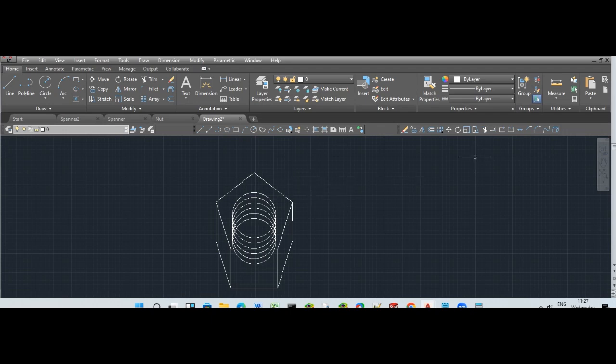I will click this tool here, click the trim tool, select the first one, and press enter. Then I'm going to trim the other ones with respect to this. So I click here, I click trim, you see it's going off, trim, trim, trim, trim, and I press enter. Ooh la la, we have this beautiful knot looking at us.